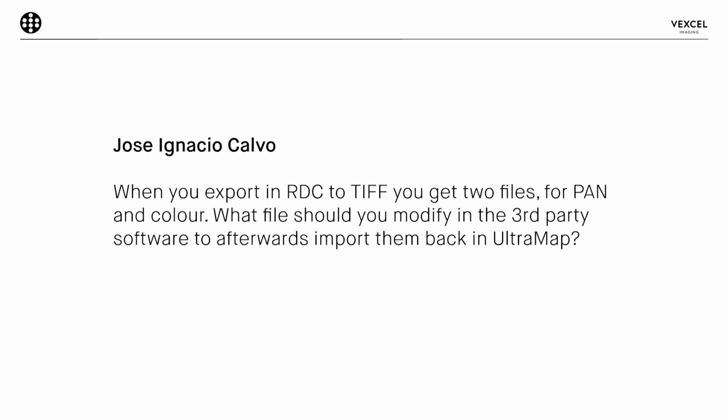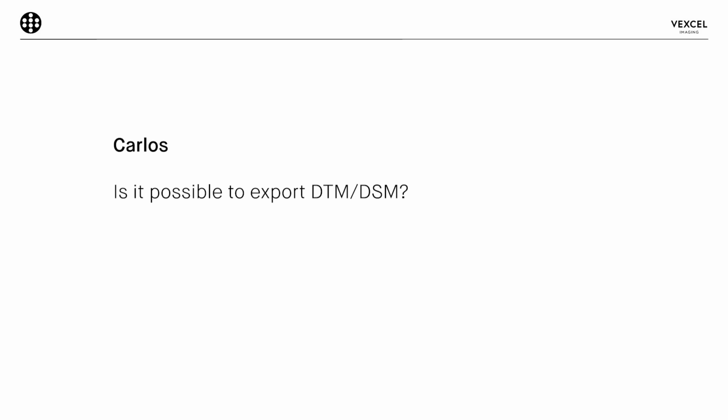Good. Next question, is it possible to export DTM, DSM? Yeah, so we support the file format GeoTIFF at the moment for exporting the data. As an option, additionally, we write world files. Additionally, there's also the export for point clouds in the LAS file format.